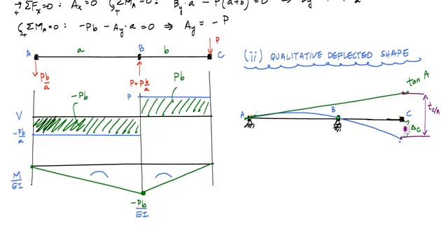So is there a way that I could calculate this distance right here, which I'll call D for now? The relationship between t_CA, delta C and D is that delta C is equal to t_CA minus D. And I could calculate this D by using some small angle approximation.